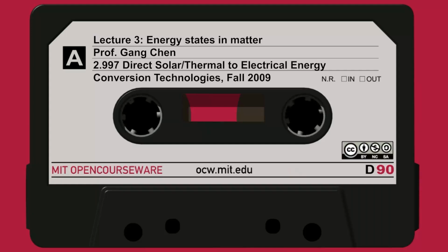So how do I determine the chemical potential mu? If you give me the number of dopant, so I put phosphorus in the semiconductor per unit volume, I know how much I put. And if I assume each phosphorus donated 1 electron, that is an assumption, and there are more rigorous statistical ways to see how many electrons are activated. But because the phosphorus energy level is so close to silicon, you can roughly approximate this. Every atom that you put in there donated 1 electron.